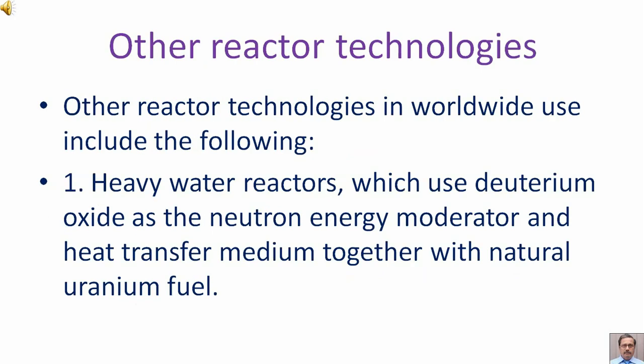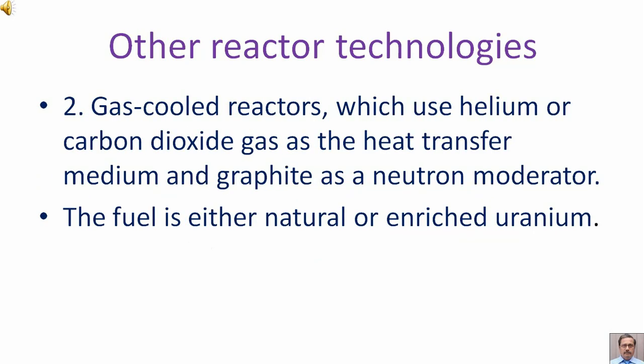Other reactor technologies. Other reactor technologies in worldwide use include the following. First, heavy water reactors, which use deuterium oxide as the neutron energy moderator and heat transfer medium together with natural uranium fuel. Second, gas-cooled reactors, which use helium or carbon dioxide gas as the heat transfer medium and graphite as a neutron moderator. The fuel is either natural or enriched uranium.